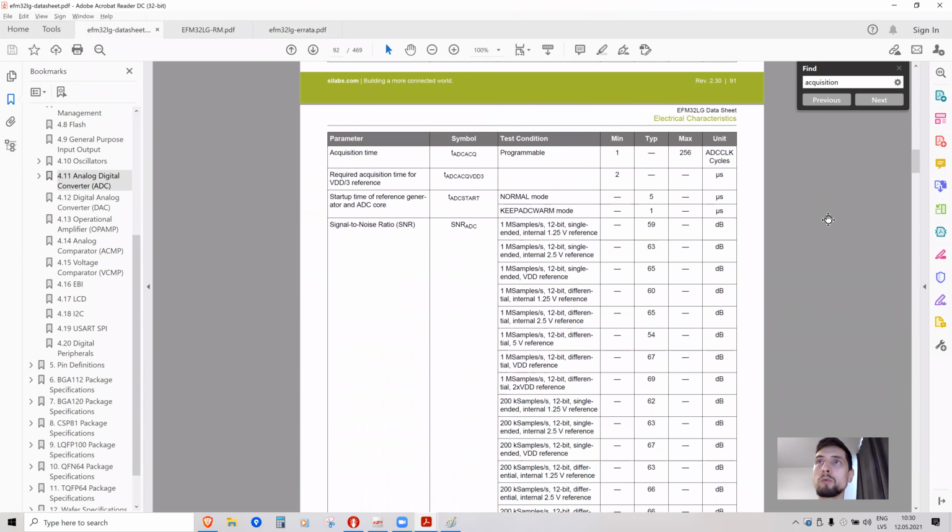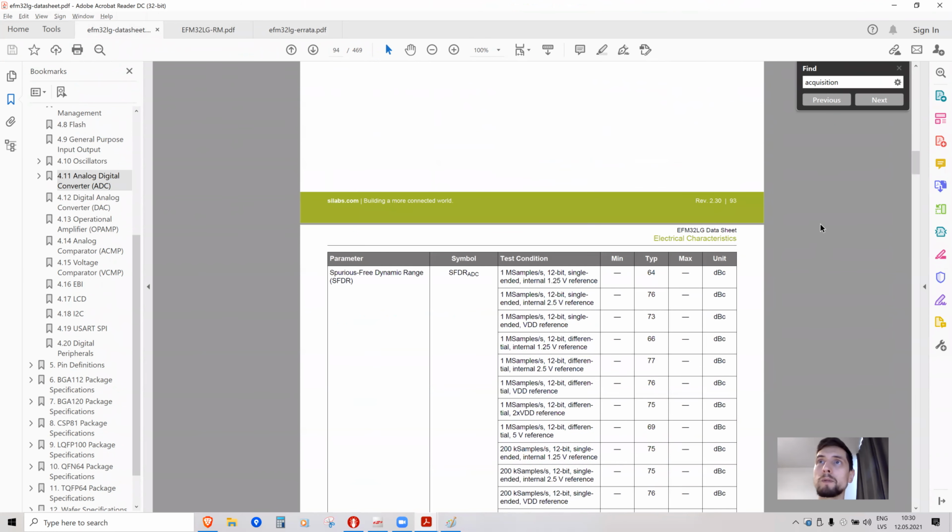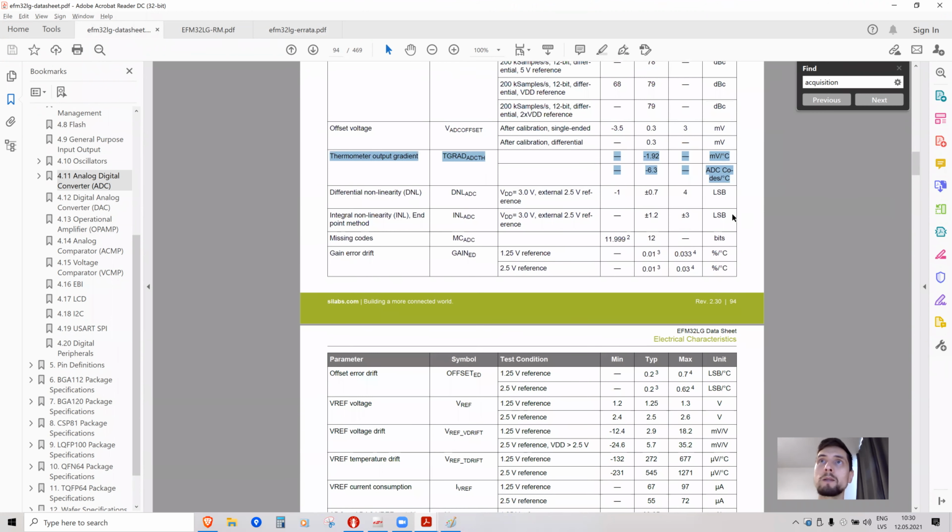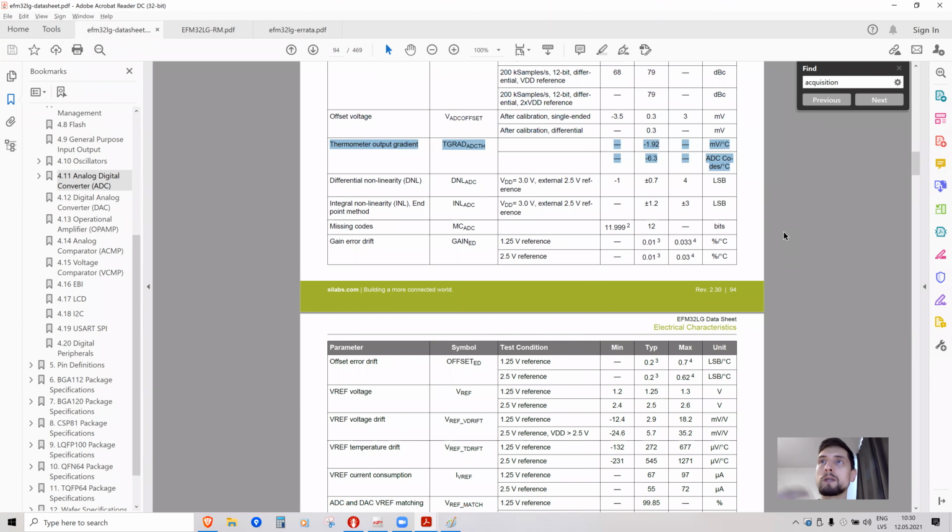If you build 100 devices and take them to the lab, their temperatures will be plus minus 1 degree in precision, right? So one device will say 26 degrees, another will say 24, some other will say 25, and so on. So the temperature sensor is not meant to be extremely precise. There's no need for us to calculate the temperature with 5 numbers behind the decimal point, because it's just plus minus 1 degree.